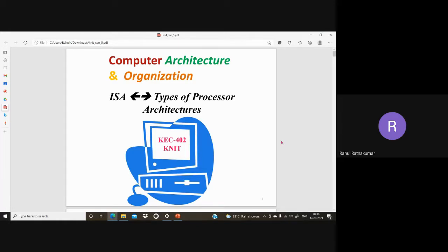So based on all those hardware structures, we can have combinations and permutations of loops or operations, maybe adding multiple bits, maybe squaring, maybe a series of n numbers, logarithm, exponential, a lot of things we need the processor to do. Some of these can be directly accessed by a single instruction, some may be a combination of instructions. For example, we can do multiplication by repeated addition. Likewise, this instruction set will give you an idea what the processor can do or what hardware it is having.